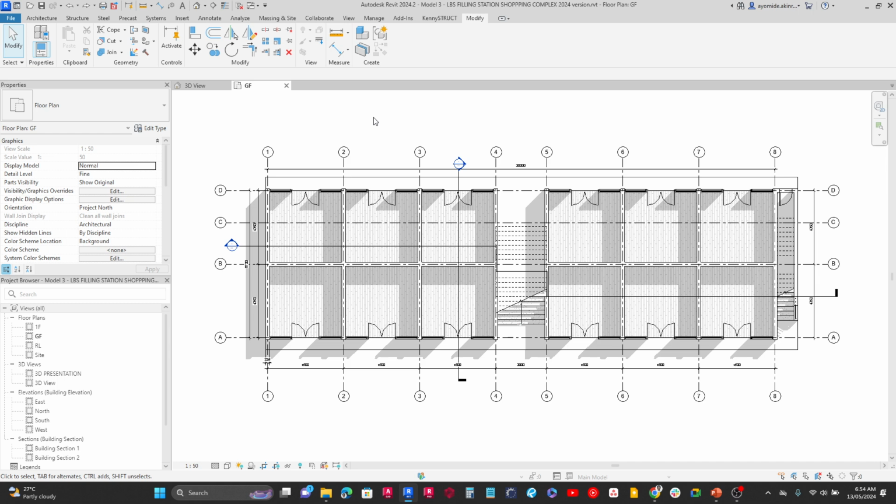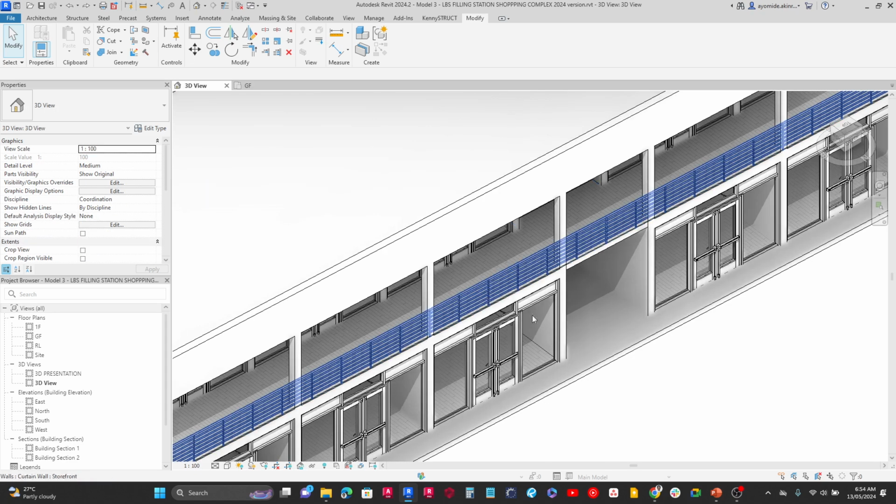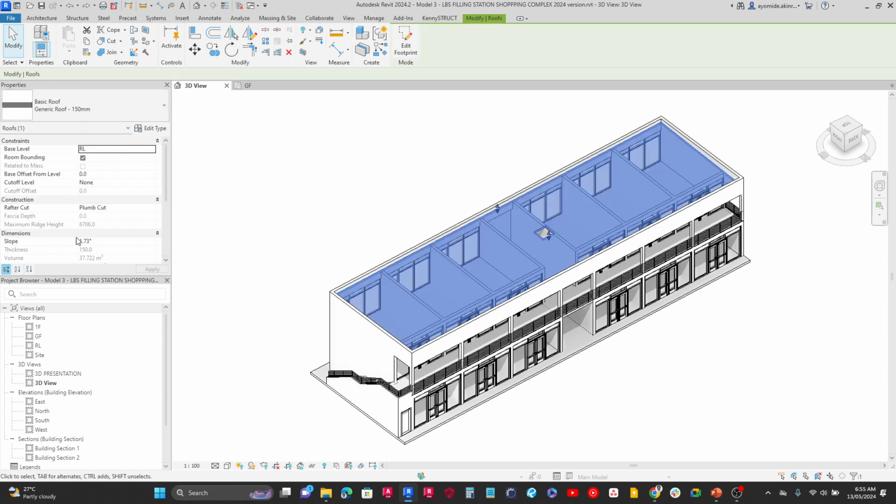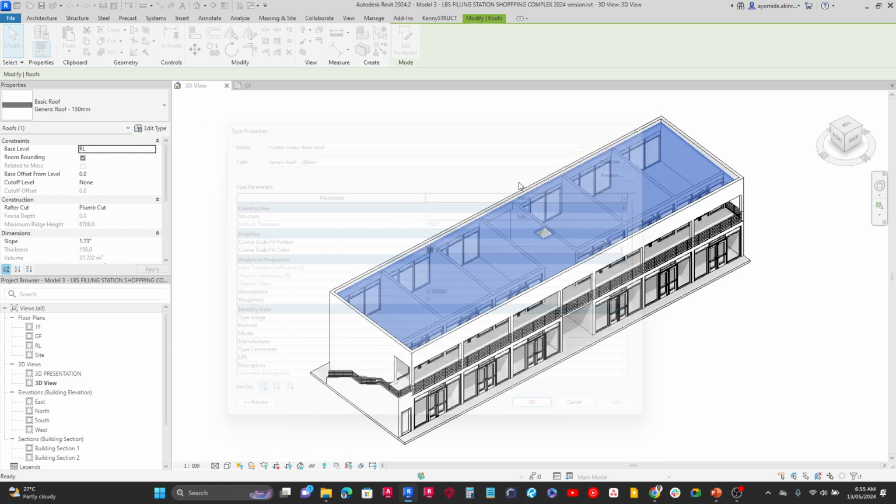Okay, so as a recap, we looked at how we start off by looking at a project, by loading it up in Revit. I talked about the compatibility. For instance, if you're using an older version of Revit, you can't open a model saved in a newer version. Likewise, I also talked about how to look at the properties of whatever you've selected in Revit. So for instance here, if I select this roof, I can see some of the properties of the roof as well as the thicknesses. And over here I talked about the family type as well.